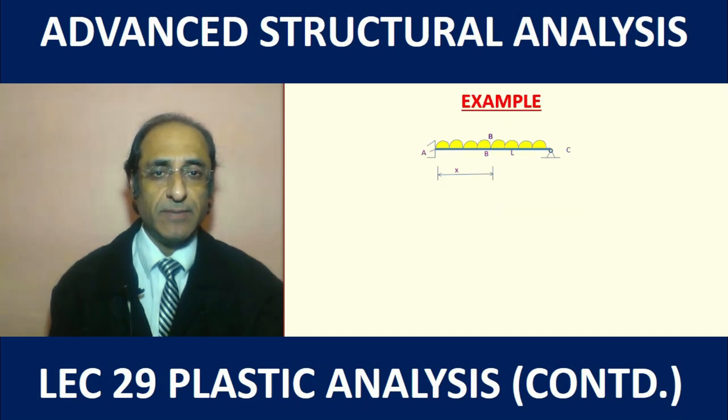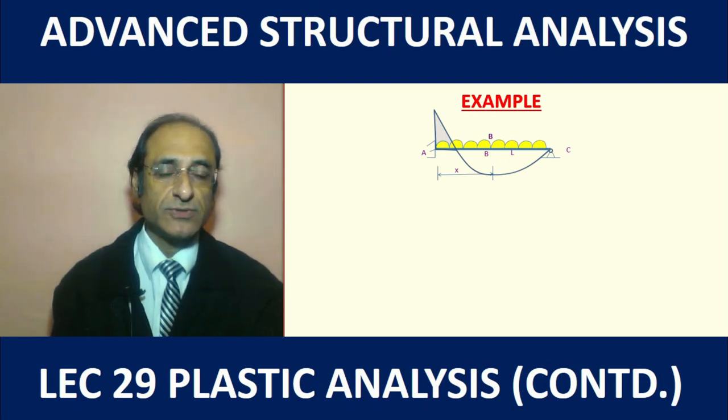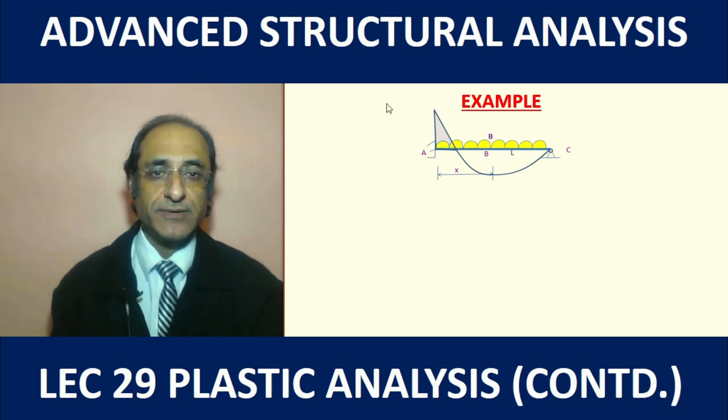So let's apply this principle on a beam. Here we have a beam which is a sort of propped cantilever, and this is under a UDL. For the method we are using the method of virtual work, so we don't need the actual values involved with the bending moment diagram. We just need to know the qualitative shape of the bending moment diagram. For example, here we don't need to compute the values of the bending moment at the key locations as per the elastic analysis. In the longhand method, we need to determine these values from analysis, so this step is not required here.